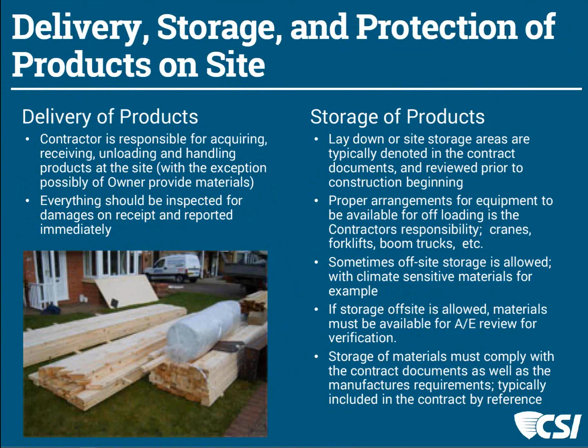But sometimes we have provisions for off-site stored materials. In the state of North Carolina, that's a rarity, especially for state-owned properties. They want the materials on the site because they want to pay for them on their property. Should something happen on the job and things go badly, then it's easy for them to recover. But sometimes things are stored off-site, particularly if it's a climate-sensitive product or material.